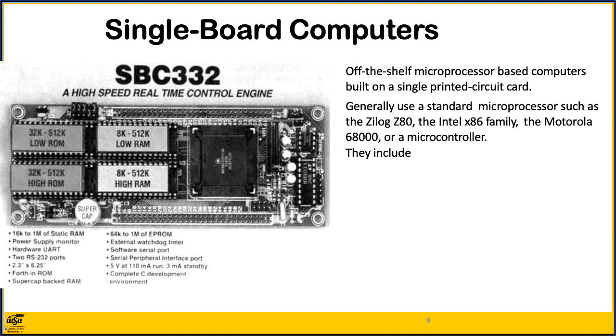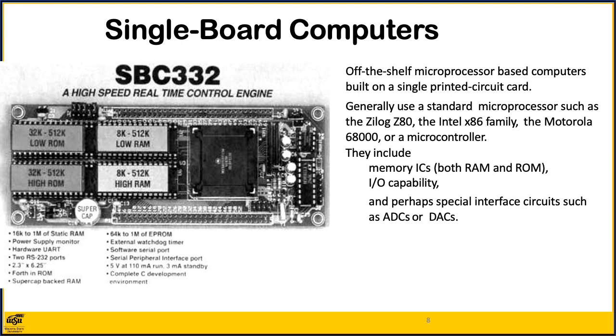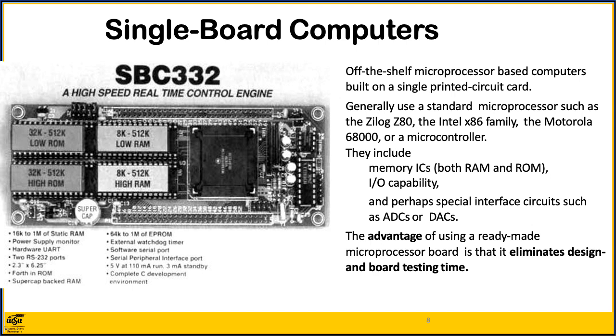They also include memory ICs, both RAM and ROM, I/O capability, and perhaps special interface circuits such as ADCs or DACs. The obvious advantage of using a ready-made microprocessor board is that it eliminates design and board testing time. This is particularly important in small volume production or one-of-a-kind systems.